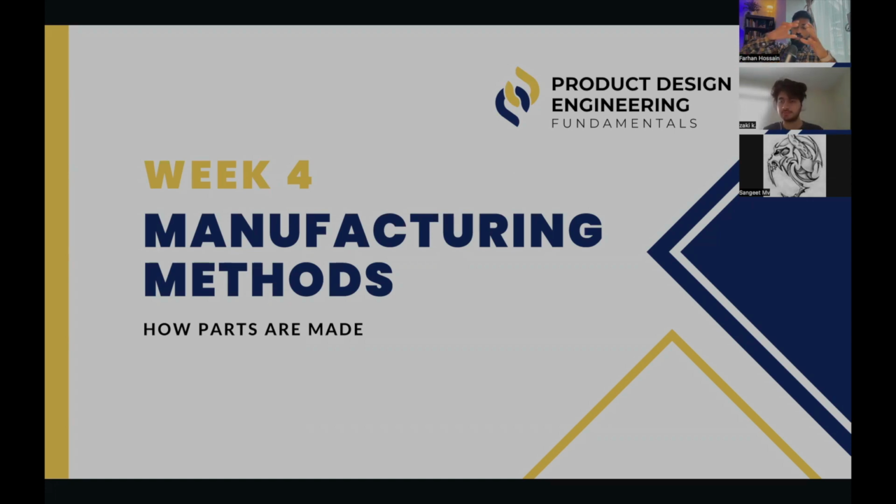So yeah, the actual what's happened. Well, we'll learn a bit more. Actually, we don't have this process today, but it is a process called deep drawing. You actually stamp out this big disc, and then you put the cylinder and you squeeze it. The reason why you don't make it a tube and then bond it is you'll see that there's no seams, and the reason why it might be because the seams could have a failure point where liquid might have escaped or it might be not consistent, right? So anyways, we'll look at different ones today and chat about them.